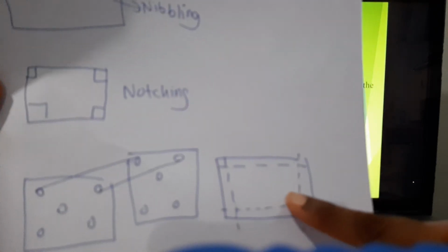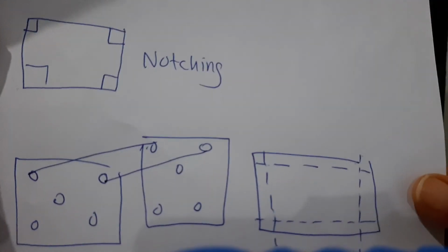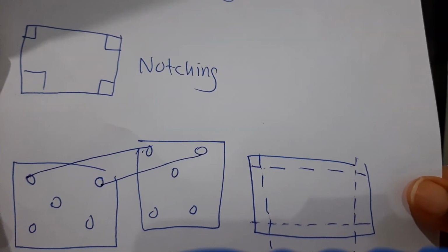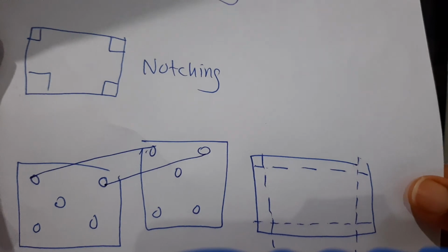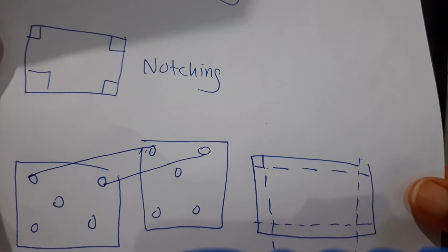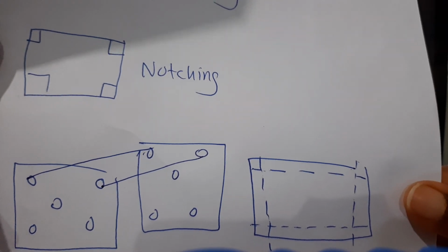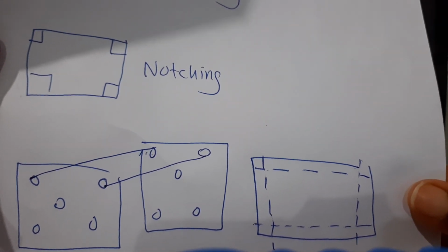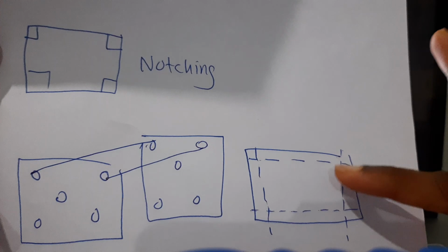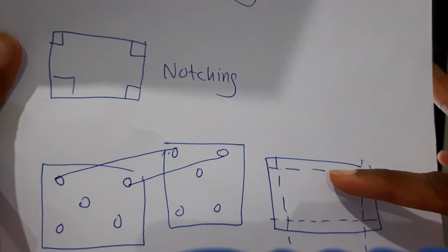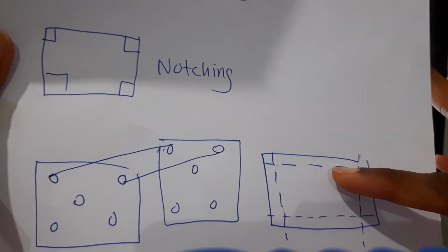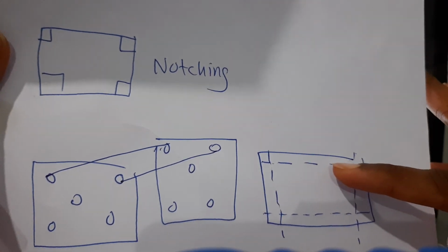Looking at this, this is lancing. You're going to create indents on that sheet metal material. Why are you creating indents? If you don't create the indents, when you bend the material, you're not going to bend it properly. Normally, if you want a sharp 90-degree bend, you must indent the material, creating an impression on it.